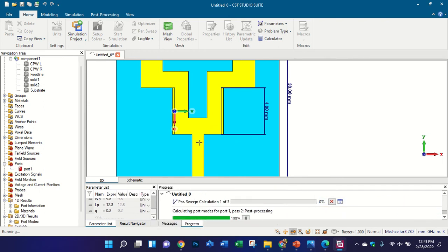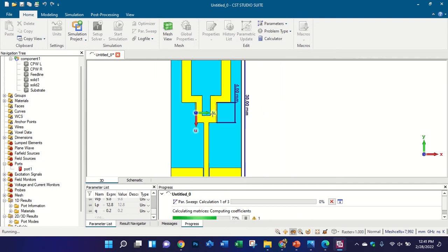And you can see the difference, because you know, with the surface current this portion is highlighted with red color. So it means if you change this position, or subtract any slot or add any slot here, then you will have a difference in your frequency bands.